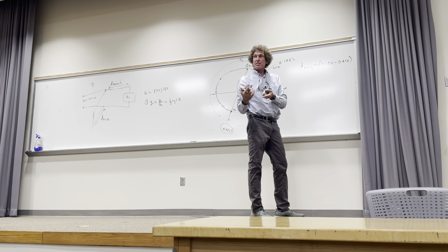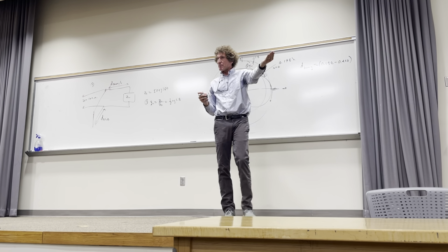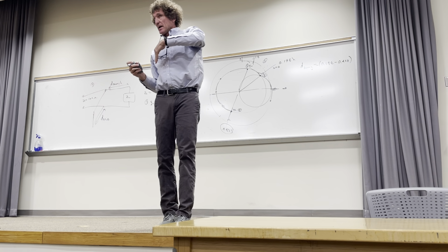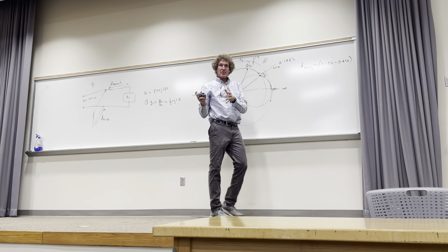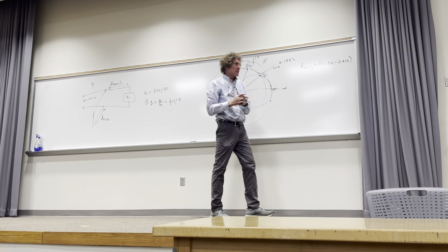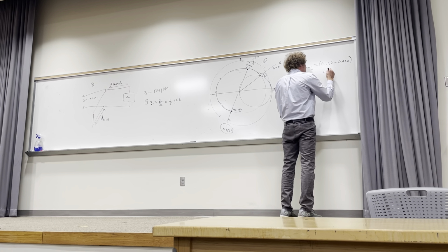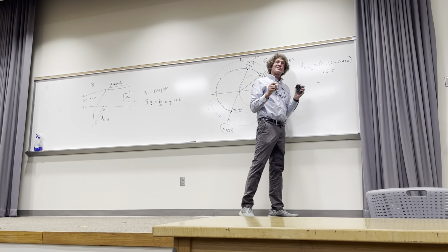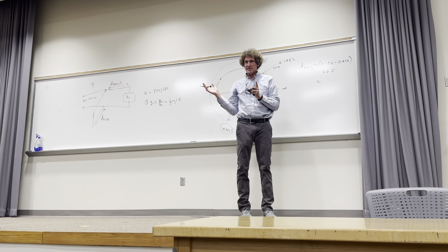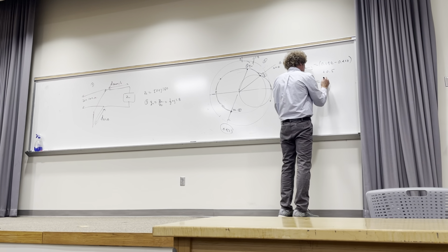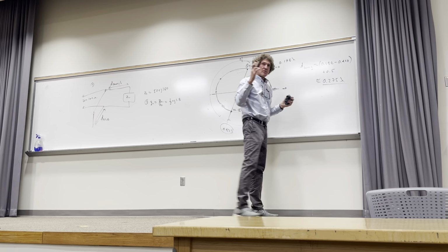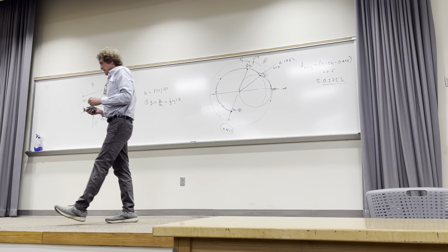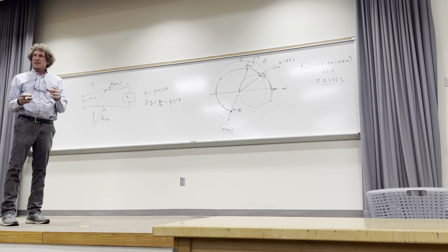Do y'all follow me in this class? Remember, you go to the point you're going to end up at, and you subtract the point you came from, not vice versa. Some people took 0.422 minus 0.198. That's the wrong answer. Do y'all follow me? You have to add that half wavelength. So then I add a half wavelength to this, and I think it's 0.275 or 278, something like that. Is that right? So it's 0.275 approximately lambda. And I gave people wiggle room there because I know the Smith chart is an inexact instrument, but that gets it down there. Now that is the length of the through line.